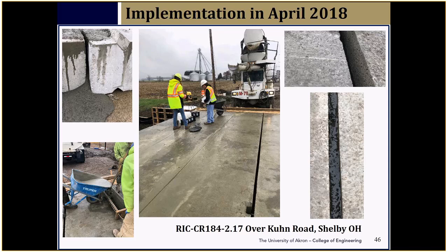If you see the figure on slide 46, bottom left hand side, you will see the grout workability in the picture. It's really flowable grout. On the right hand side, the picture shows you the grout inside the recess of the keyway, which is really flowable actually. I think that was very workable. So we did not need vibration. That's the intent actually, because it's very difficult to insert a vibrator into the keyway recess.